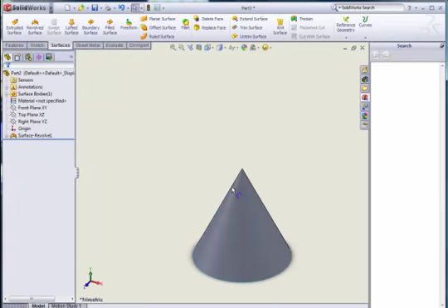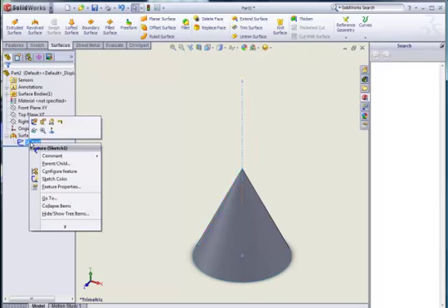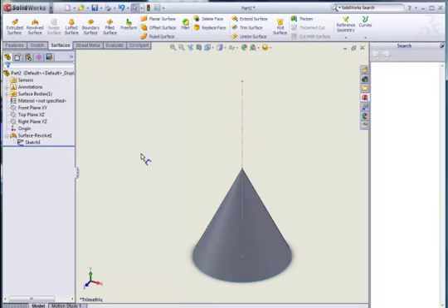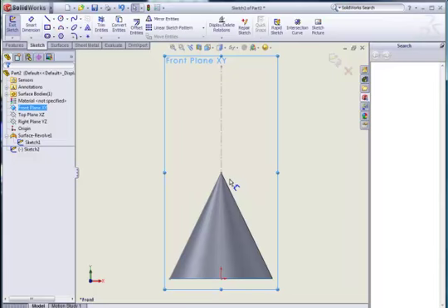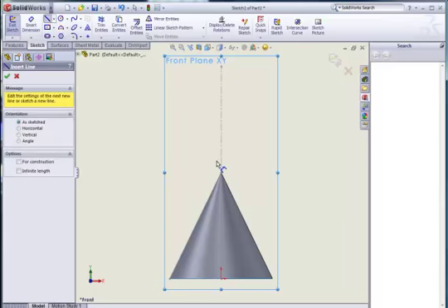So there's our first of our double cones, and we're going to need that sketch for the second one. So if we expand the first surface revolution and right click sketch and show sketch. So now if you open another sketch on the front plane and look normal to.